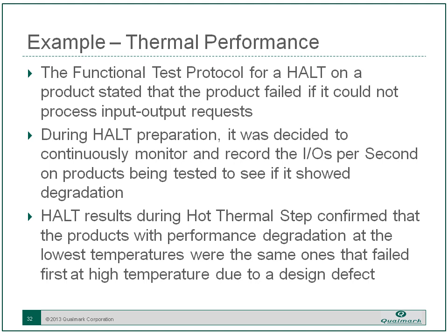Due to the nature of the test, there was always some variability in the number of IOs per second that it was processing. But as we increased temperature and decreased temperature, we could watch and see if the IOs per second changed. And during HALT, we saw during the hot thermal step that performance degradation.